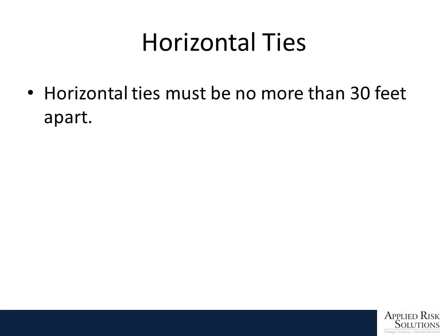And as you go down the length of the scaffolding, once you have to start tying it in, it must be tied in at least every 30 feet. So if you had a 90-foot section, you would have 3 tie-ins, one on each end, and then you would come into the middle, have one at 30 feet and another one at 60 feet. You probably have 4 actually.